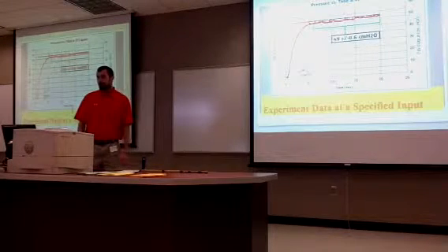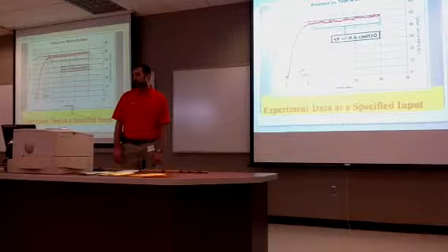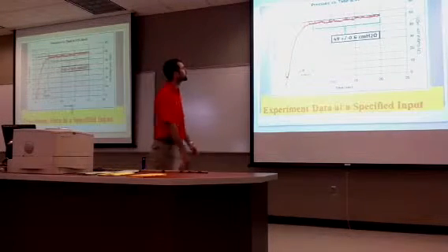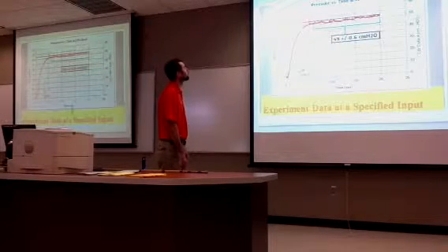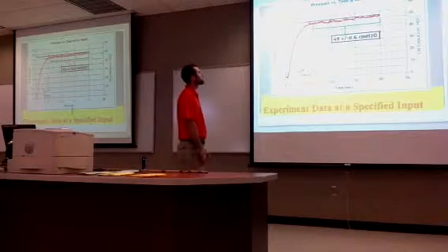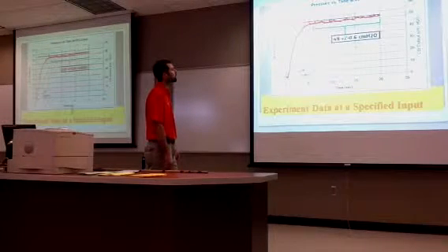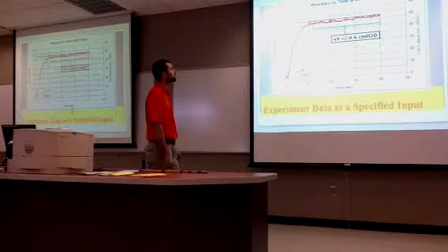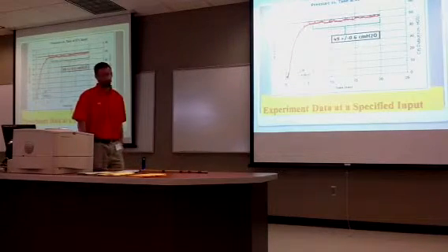This is pressure versus time at 85% input power. This was used in the beginning of our constant input values, and we were able to find a steady state of 49 plus or minus 0.6 centimeters of H2O over a duration of 15 seconds.